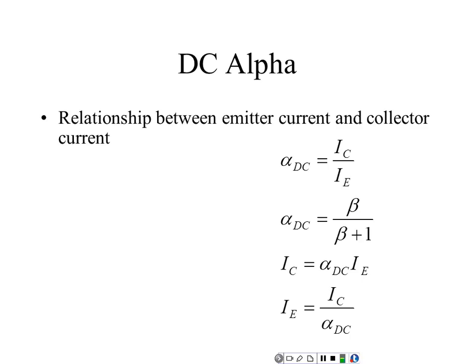When we deal with common collectors, we are going to deal with the alpha of the transistor. Common emitters are used to get a bunch of voltage gains. Common collectors are for current gains. Common emitters are for voltage gains. So we usually use common emitters to take the input from that little old tiny DVD disc coming in, and we'll get a bunch of voltage gain out of it. And then when it comes time to drive the speakers, we're through with voltage gain, right? You understand? And what we're looking for now to drive a speaker? Current. Yeah, that's what makes a speaker work is current. It creates a magnetic field.